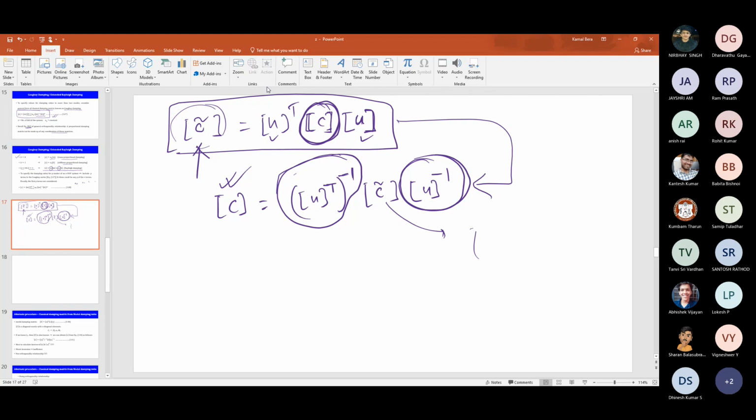Obviously you will say direct inversion, but direct inversion is not an efficient approach. Also, if you do not consider the full modes and you have truncated them, then it will not be a square matrix. That will be n cross n hat, remember? So you cannot invert it. The best idea is to use the orthogonality relationship again. So what is the orthogonality? U transpose M U, let's say it is mass normalized, is the identity matrix. Agree?